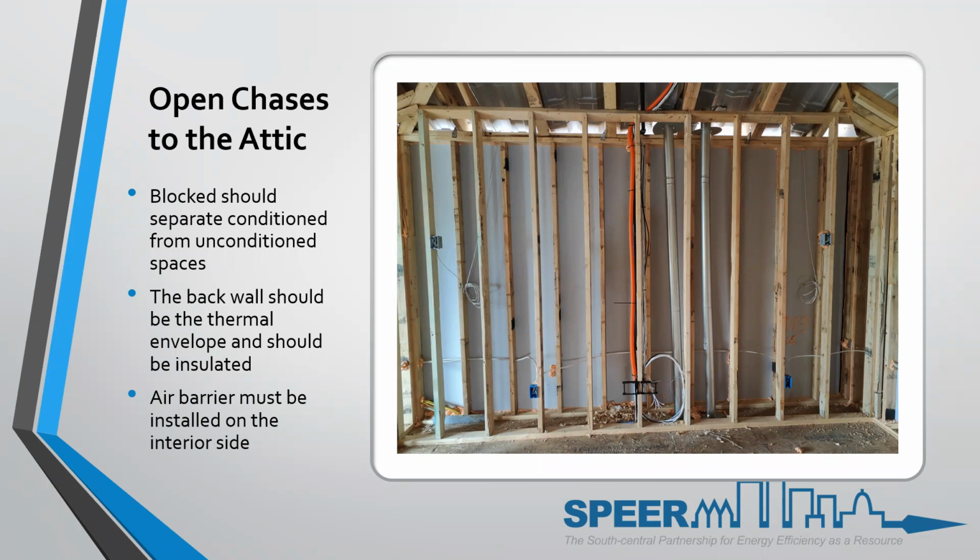You can just do the insulation on the front wall and then air seal the back of it with a T-ply or OSB and then sheetrock on the front. Now that makes you have the front wall as your thermal envelope. It's really misaligning it. It's jutting it out into the room. It's misaligning it with the rest of the home. It's also where that Smurf tube comes down. You've got 2 open boxes that aren't air sealed. There's no way to air seal those. And you're going to leave those open to a chase that actually is open to the attic. Not a good idea. So insulating the back and then putting T-ply on the back is the perfect way to air seal and keep the envelope aligned.